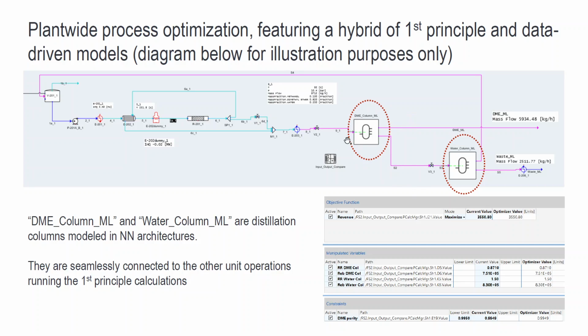So even though this is simple, we have the kinetics and we have some recycles. Simulating with the actual distillation columns over here and over there, we will experience unconvergent situations, let alone if we want to optimize the performance of the plant, right? So we have two obstacles there: the convergence issue, and finding the optimum solution.